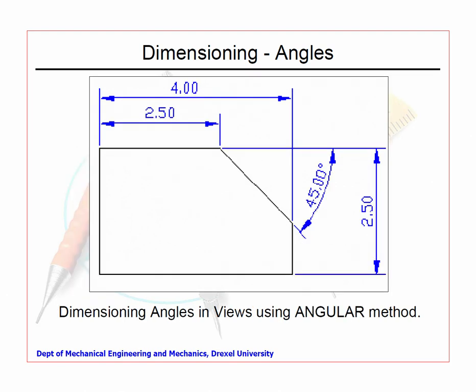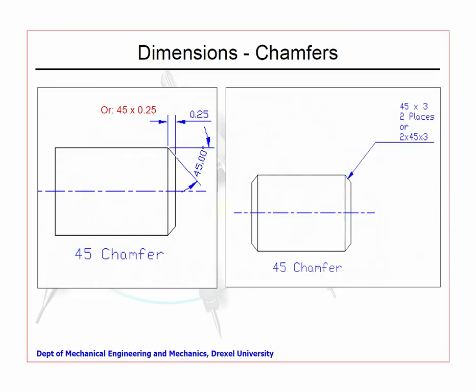Setting is something else. Then in some conditions, angular dimension is preferred, and in some even other rare cases, if it is a taper, both the taper angle or the taper step is mentioned here, saying in this case both is 1.5 by 1.5, instead it will say 1:1 with the other dimension, saying how many millimeters down it is for a given length, which is another way of representing those things.